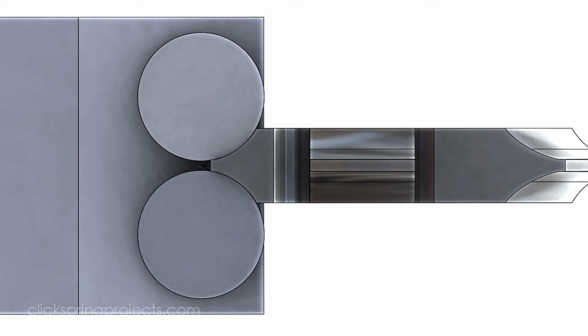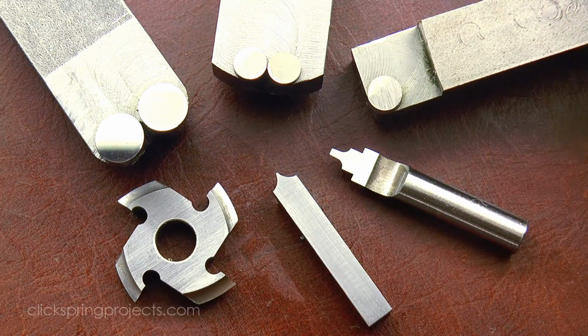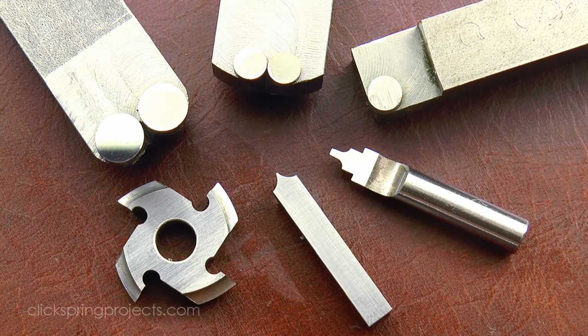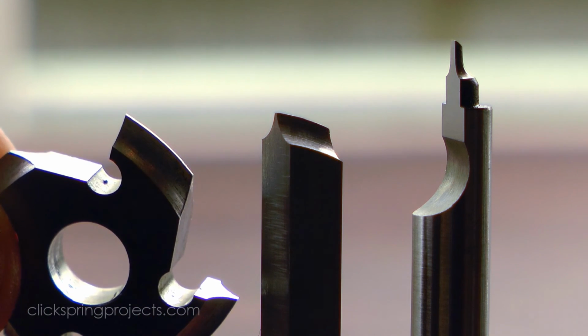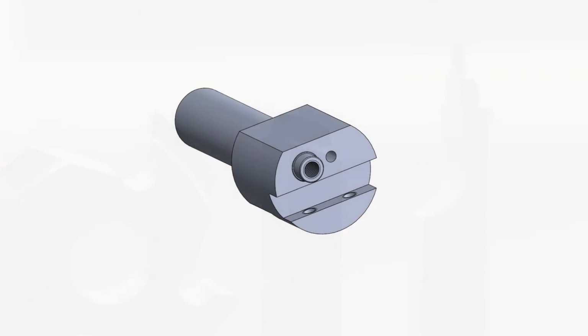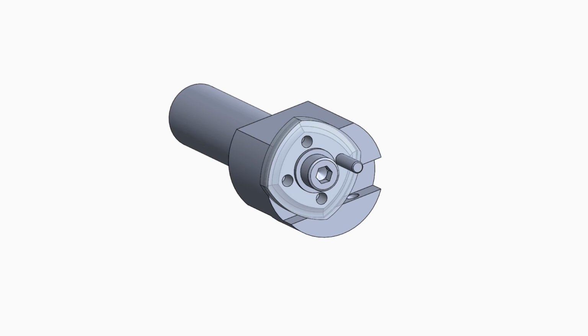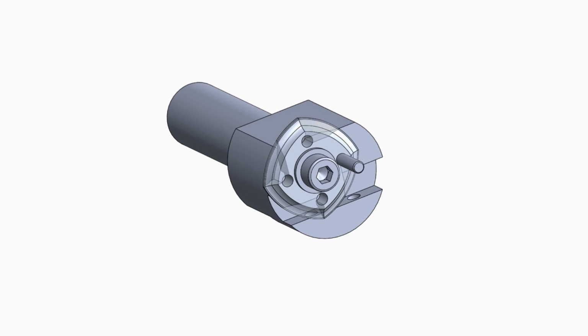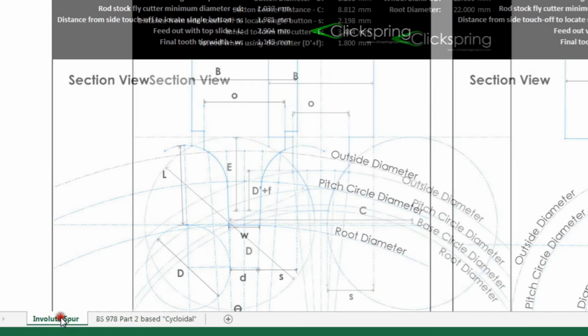Now what we've just covered is the basic engineering premise that underpins a range of button cutter methods that have been serving clockmakers and model engineers for decades, each with their own set of compromises depending on which route is taken from here regarding solving the form relief problem. We're most interested in a straightforward solution that'll still give professional results. And one method that fits the bill well is an arbor that carries the cutter blanks eccentrically. It permits a very straightforward profile relief to be generated on a multi-tooth blank as 4 distinct lobes, and then a section of each lobe is milled away to reveal the cutter faces. So that's the basic idea.